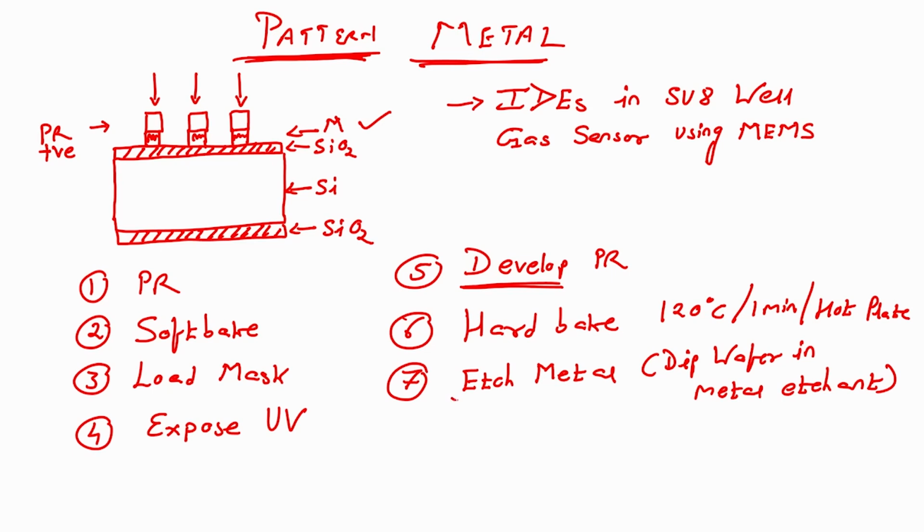So, when I etch the metal, the metal which is protected by photoresist, this is the one, 1, 2, 3, will not get etched. Where is photoresist? Photoresist is these boxes. Metal which is not protected by my photoresist will get etched. So, when I etch the metal, I will have this particular thing.